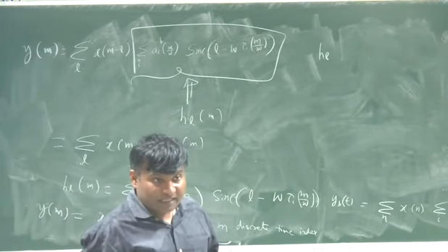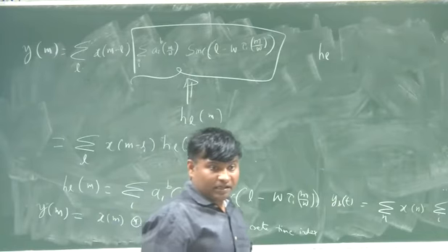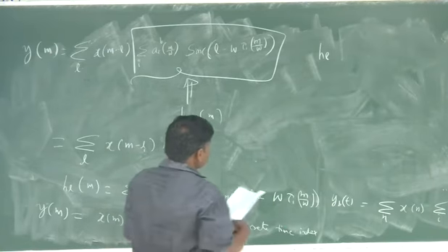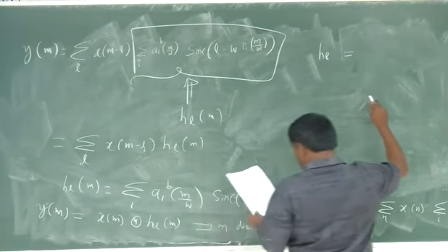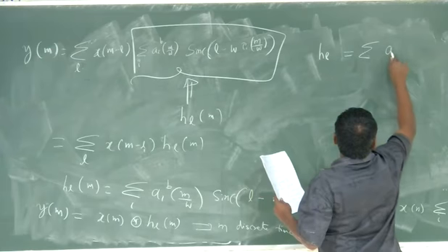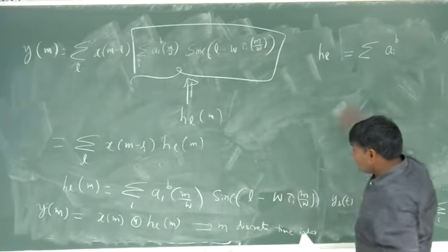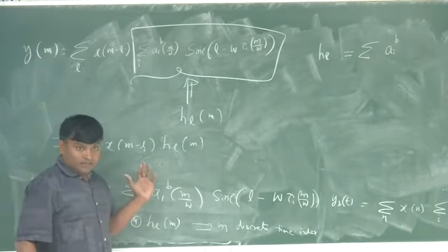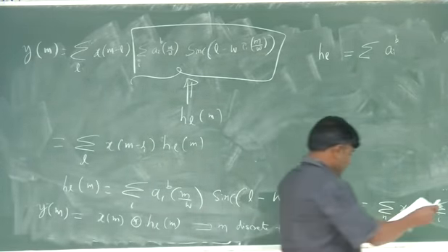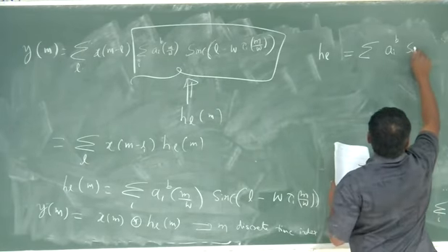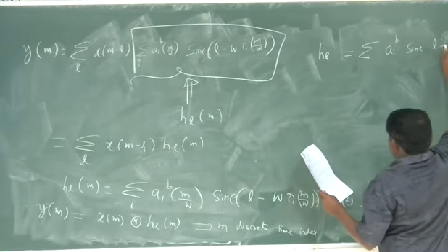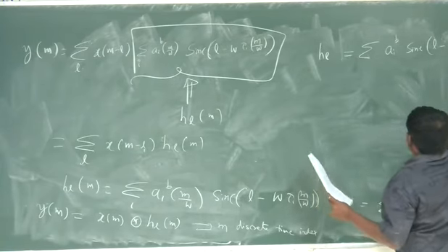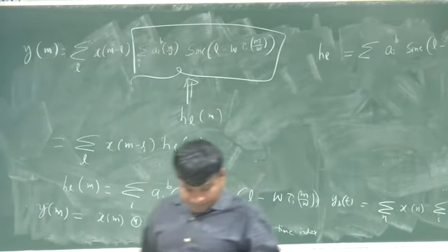If the system is time invariant, the channel impulse response should be independent of the time index. That would be H of L, and that would be a_i b, and whatever is in the bracket is a function of m, therefore it is independent of time. So we don't write it as a_i of b, which is a constant, sinc L minus tau_i into W. You agree with that?